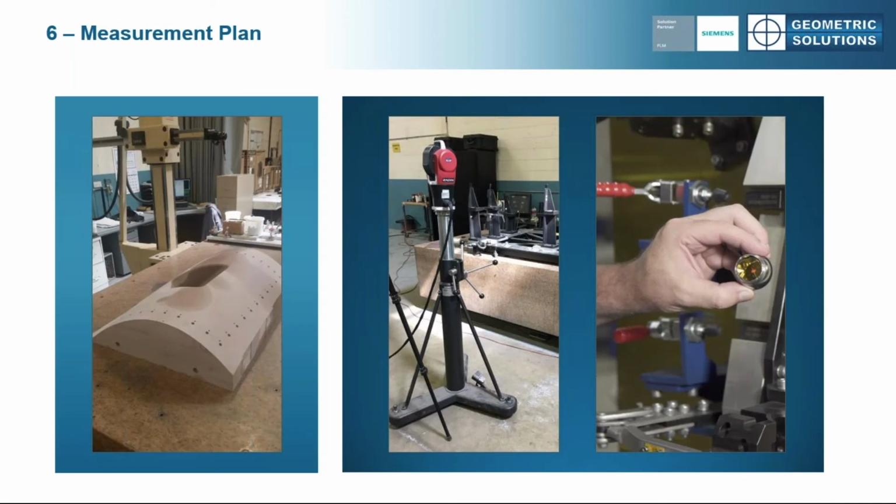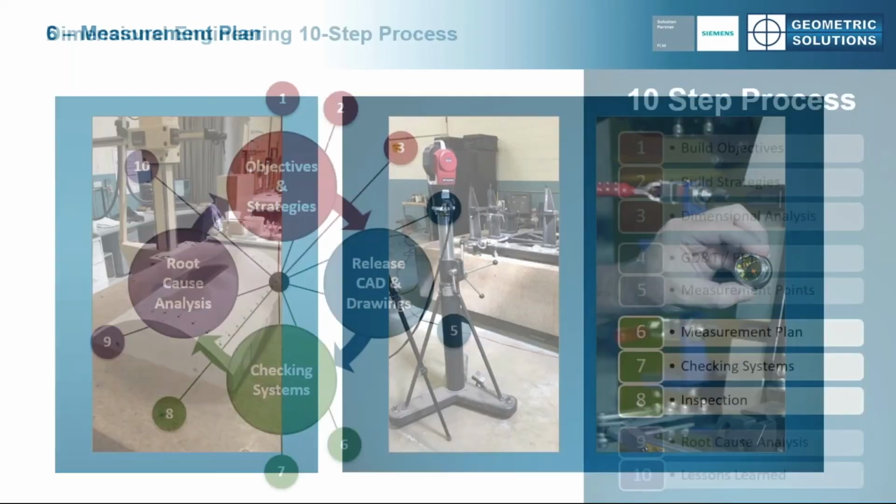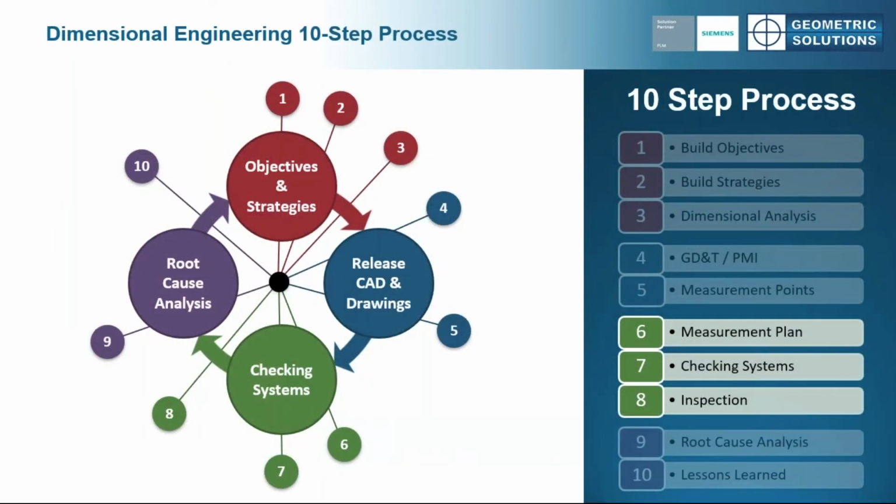I have coordinate measure machines on the left. I just can put my part on my table and measure it. I have things like laser trackers that can go great distances. I can go 300 feet on that laser tracker and be accurate within a couple thousandths or less actually. So we just got to have a plan for what kind of tool and the frequency so I can make sure we're going to have things covered and the budget is there to use those tools properly.